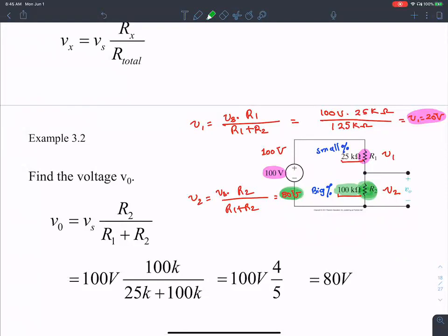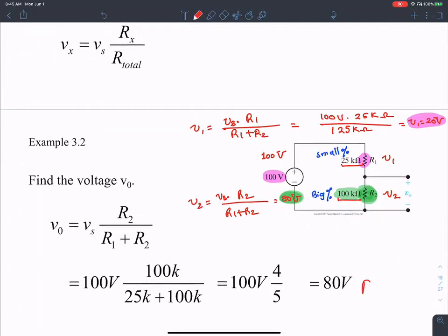So that's the idea of voltage division. If you want to find the voltage across resistance R2, then you simply take the total applied voltage divided by the total resistance seen, times R2, because that is what we are trying to look at, the voltage drop across. Questions, please.